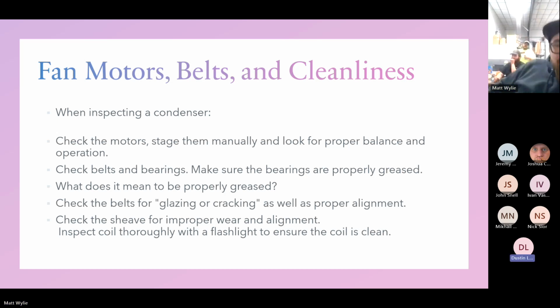Yeah, it's similar to our Albertsons here in Boise with glycol. Usually those water cooled condensers, you even see on single systems, but they always have a regulating pressure switch type thing that you adjust to adjust the flow of the water. Because obviously, if you're not moving enough water, you're building up more heat and you're going to have higher head pressure. So if you are working on a water cooled condenser, having it set for the proper pressures is important too.